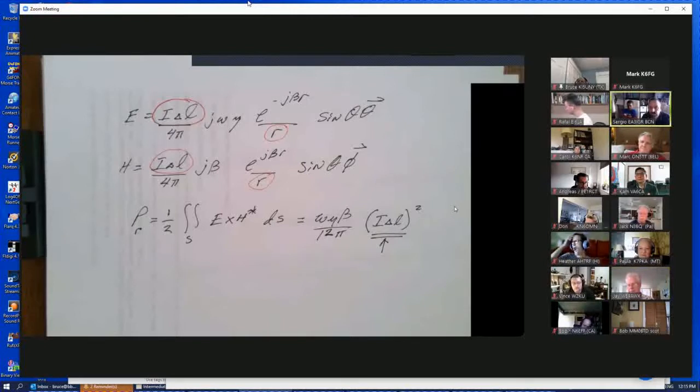So when we compare the radiated power of the dipole to the vertical antenna, from that expression for a given intensity, the radiated power of the vertical would be 1/4 of that of the dipole, because it has half of the length.